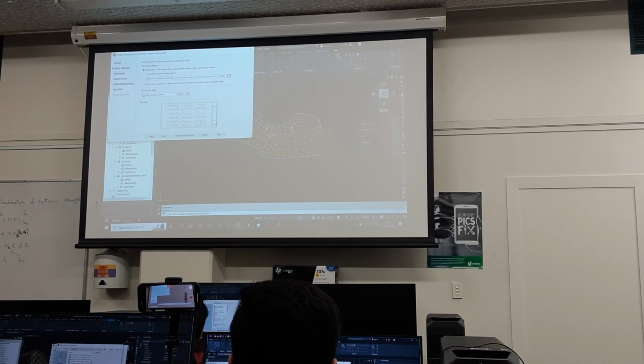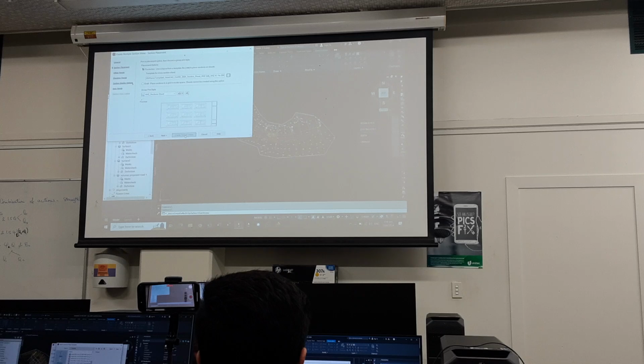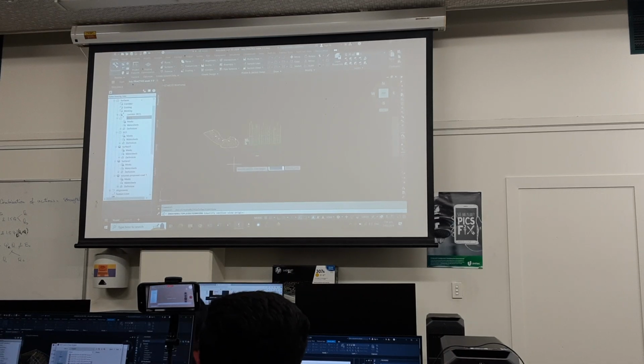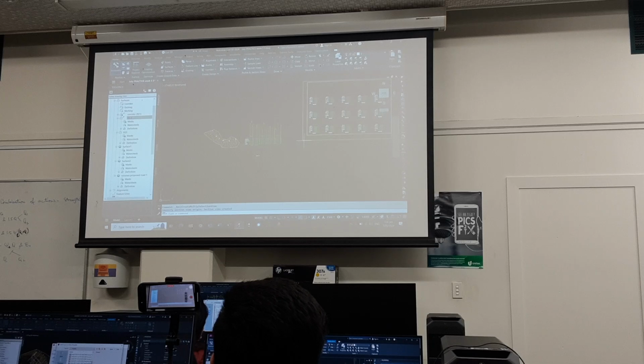And now we go create section views. I think so. Hang on, okay. Right, alright. And now I'm going to put it somewhere in the drawing. So I'm going to click down, over here maybe. Yeah. Make sure you click well clear of everything, and voila. Click to the right hand side, otherwise it'll override everything else.